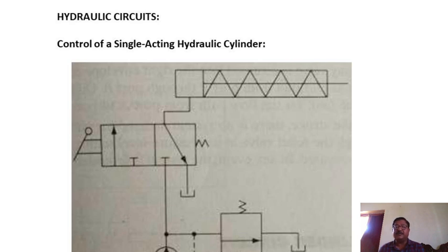counter boring and then boring and knurling, some different thread cutting and the tapering, all these operations. In that, we can't do all operations simultaneously. In the machine shop lab, we all studied that the first operation is the holding of the workpiece from both the jaws. That is done by one operation, one valve. And then after holding, the tool post has to move towards the workpiece.